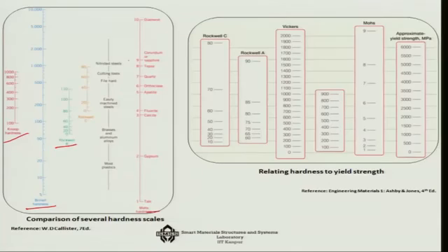For example, when you talk about nitride steels, somewhere between 1000 to 2000, maybe 1200 or 1300 is the maximum value you can see on the Brinell hardness scale. For the cutting tool, it is somewhere around a maximum value of 700. Similarly, for all other materials, like brushes, it is somewhere around 70 or so in Brinell hardness. So, this slide tells us where we expect the values to come from, which has been standardized.